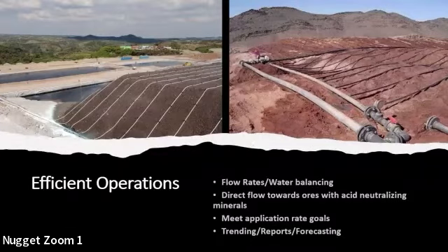After that, with all the interpretations of the geotechnical parameters, we performed slope stability and deformation analysis. Here is a general table where you can see the shear resistance, relative densities, friction angles and cohesion, which were further used for the stability and deformation analysis.